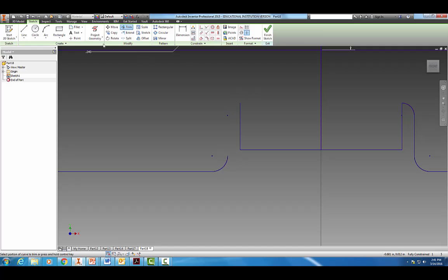Now we're just going to redraw it again to make sure everything is closed. We want those green dots because those will definitely close our loop. So I'm going to come up here, click here, and then find that green dot and click there. Very important, those green dots. Hit escape. Let's dimension it now, and we want to make sure that's 0.04. We're good, so we don't need to dimension that.